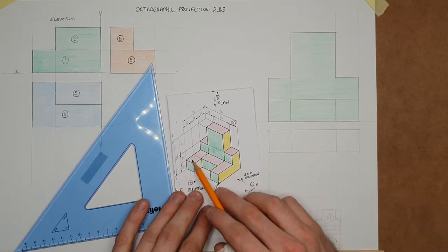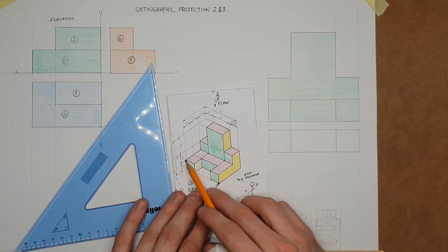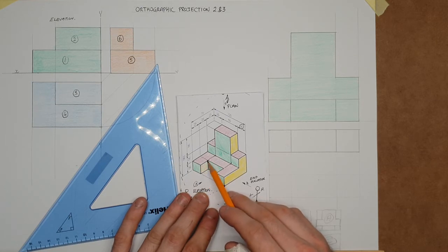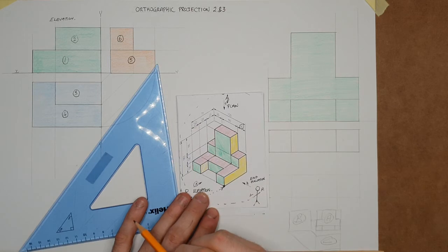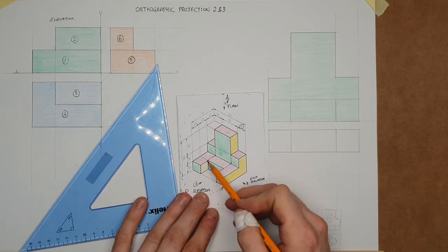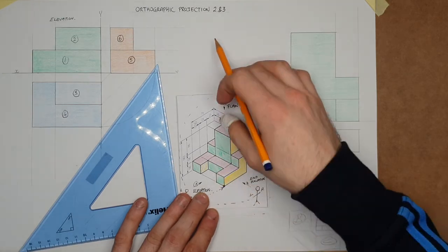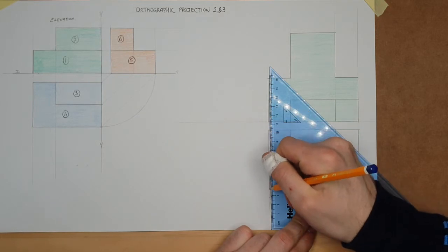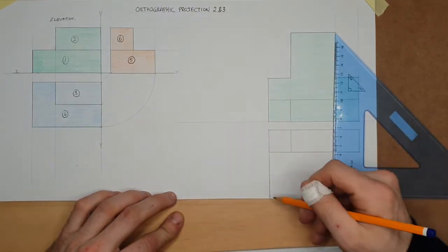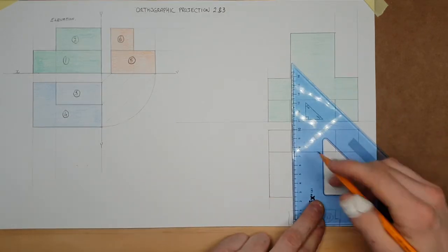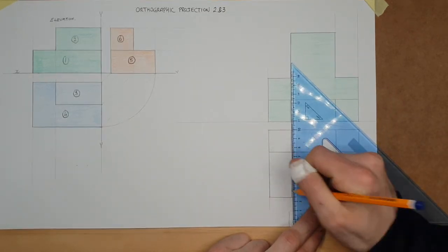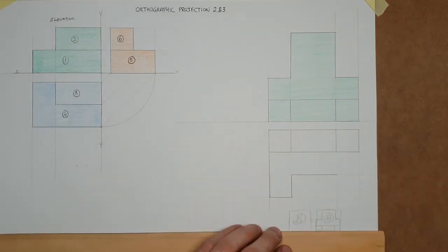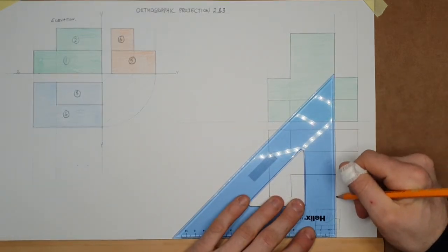And the next thing I need then is this U shape, so it steps in, so it's 25 in. If I just start looking at my measurements, I'm looking for a measurement for here, there it is, 25 up. It's 25 in, 25 up. It's along by 50, it's back out to the front again. So what are we doing? We're coming all the way out to the front. We're going across by 25 for that front little step. We're going in by 25 again. We're going across by 50, and we're coming back out.